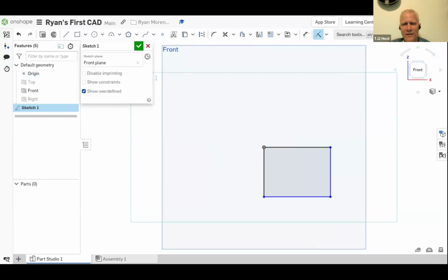Good. Okay. So now you need to put the dimensions on. The dimension is right next to the little incident icon. Move one over. Yep, click there. And now you're in the dimension mode. Click on a line, drag it up and drop it. Let's make it a 1 by 1. You click on a line, not on a corner. You can click on the corners, but then you have to do 2 clicks. So click on the line, click, and then drag. Yep, there we go, and drop. Click. Good, and then enter the number 1. It's going to be a 1 by 1.